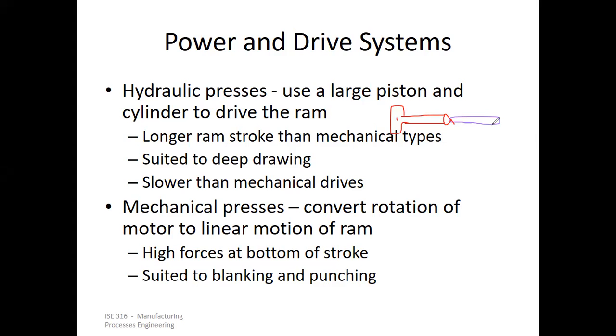Now, high forces at the bottom of stroke, suited to blanking and punching, right? Because in blanking and punching or piercing, you have this idea that the material has to be removed, right? So that requires energy, and that would come from, I mean, high forces at the bottom of stroke is another point.